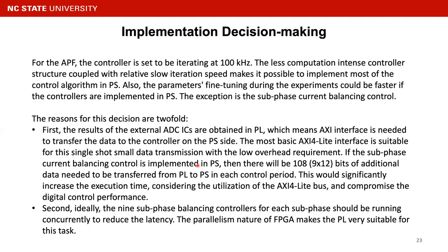First, the results of the external ADC ICs are obtained on the PL side, which means the AXI4 interface is needed to transfer the data to the controller on the PL side. The most basic AXI4-Lite interface is suitable for this single-shot small data transmission with low overhead requirement.